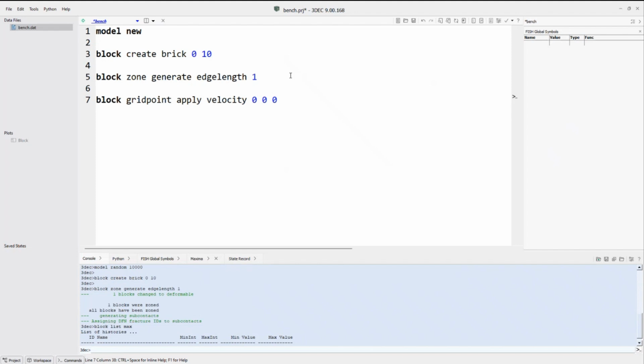So I'm going to fix the grid point velocities in all 3 directions on the bottom. So I say range, pause Z. And I'm also going to fix the velocity of all 3 components on the back. So I'm assuming there's some rock material to the right, and there's some rock material below, which I'm not going to model, but instead I'm just going to fix the boundary.